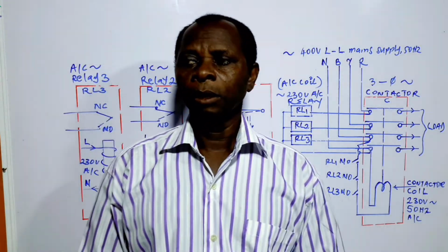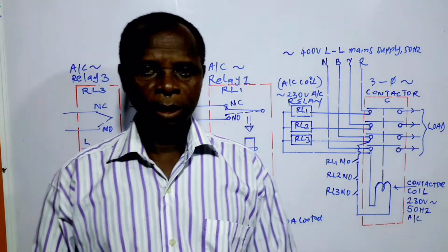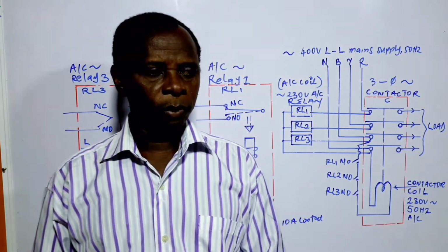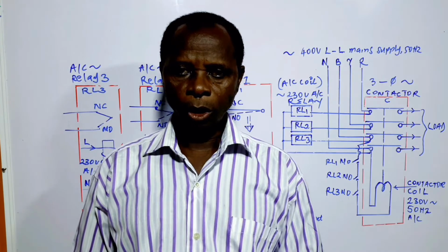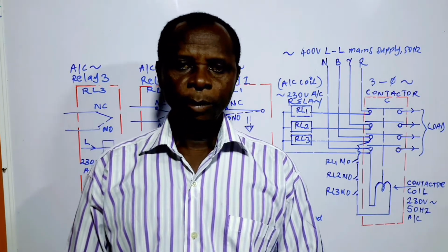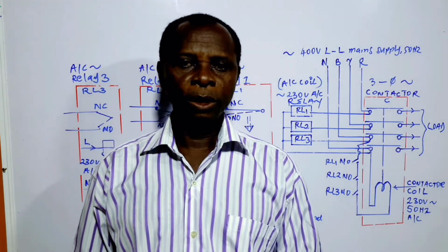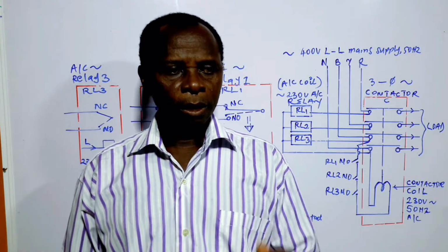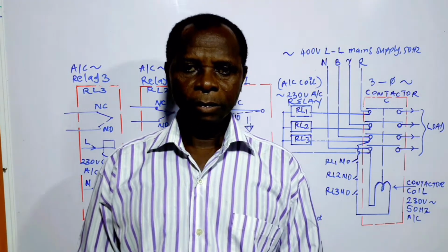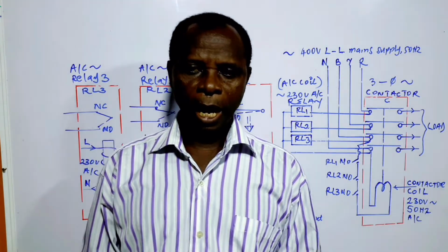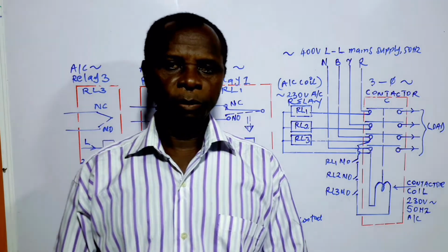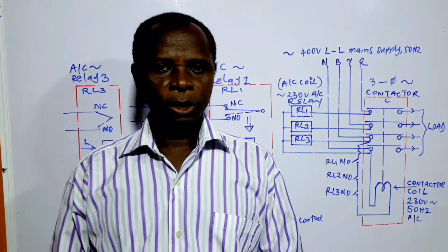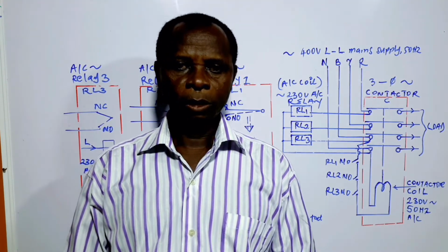The AMF device is also used to complement the function of the ATS, which is an automatic transfer switch or automatic changeover switch, by serving as a mains failure detection unit and signaling to the standby supply system, which is usually a generator, such that the mains voltage supply is switched off while the generator system is switched on.